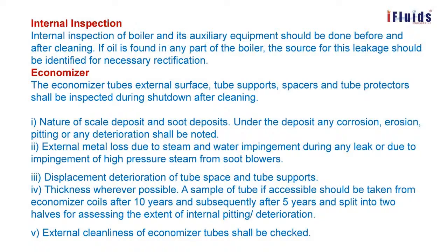Displacement or deterioration of tube spaces and tube supports. Thickness wherever possible. A sample of tube, if accessible, should be taken from the economizer coil after 10 years and subsequently after 5 years and split into two halves for assessing the extent of internal pitting and deterioration. External cleanliness of economizer tube shall also be checked.